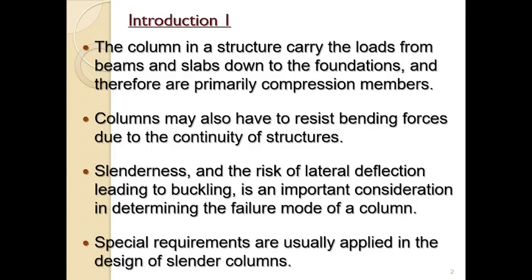As a matter of introduction, columns in a structure carry loads that come from beams and slabs, and they have to transfer this load down to the foundation, which could be pad footings, raft footings, or any kind of footings. They primarily carry compressive load, although in certain arrangements, columns may also have to resist bending because of continuity.